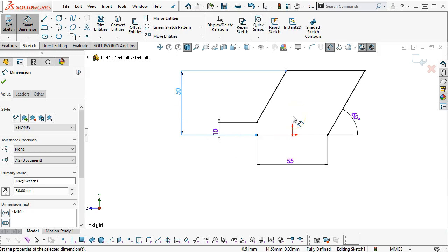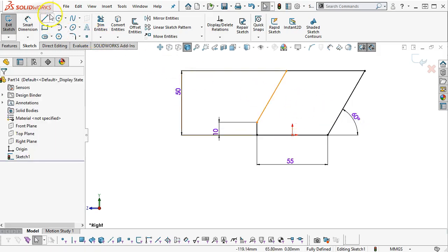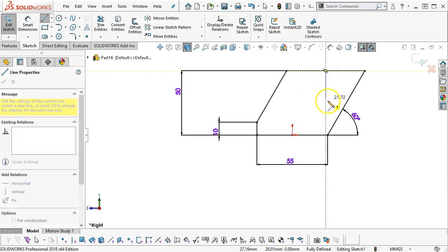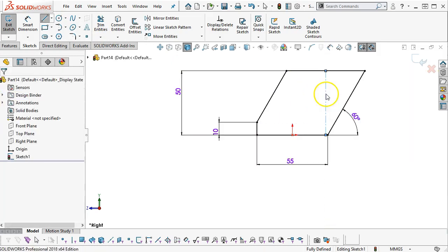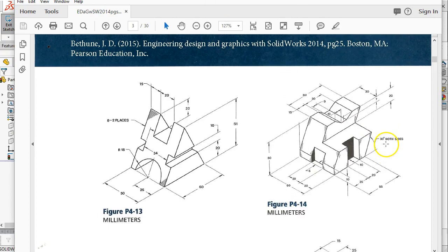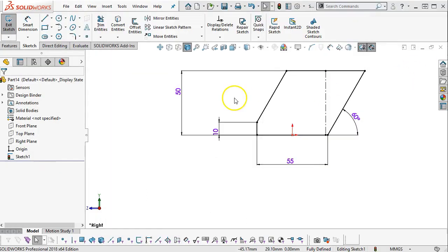All right, so those are looking pretty good. Let's come off of that top center point, and we'll just come down, make sure that it intersects. All right, so 15 and 30, and another 15 would be 60. And that came out 60.77. So that's an issue. With both sides being 30 degrees, but the slight 10 millimeter offset, no, that should still be parallel. So there's a rounding error on the 60 millimeters, or we have to adjust the angle.